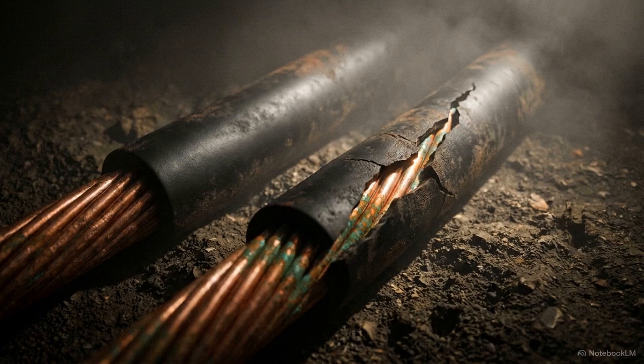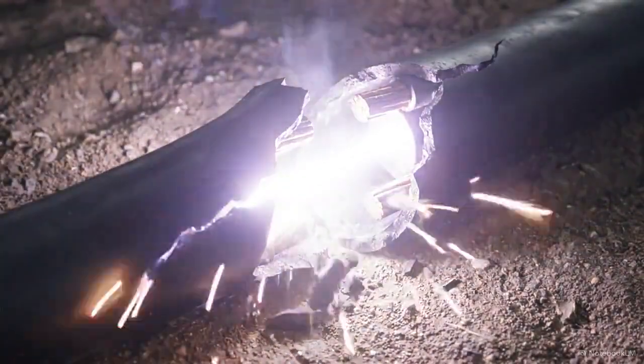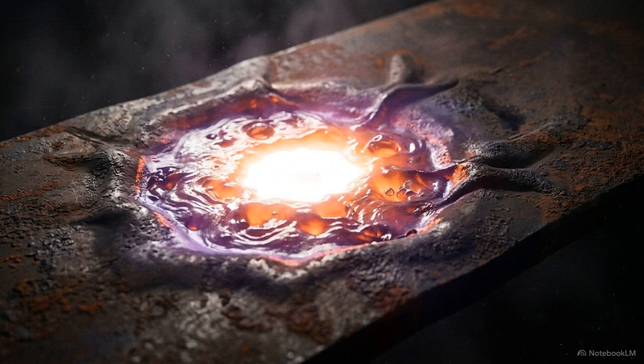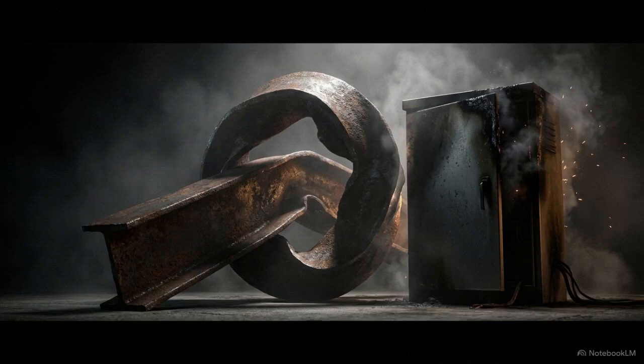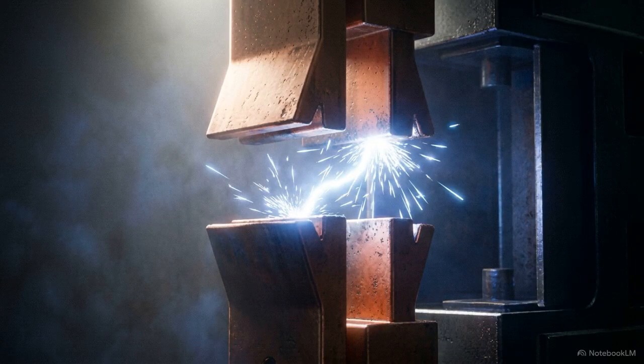Whether it's a breakdown of insulation between two conductors or a line grounding out, the sudden zero resistance state pulls thousands of amps of current into a tight space, violently breaking down the surrounding materials. That localized spike in current immediately generates severe thermal damage. It rapidly melts copper, vaporizes surrounding moisture, and creates magnetic forces intense enough to literally warp heavy steel structures. Once that runaway chain reaction begins, the grid has only milliseconds to detect the fault and sever the connection before the exponential heat melts the infrastructure completely.